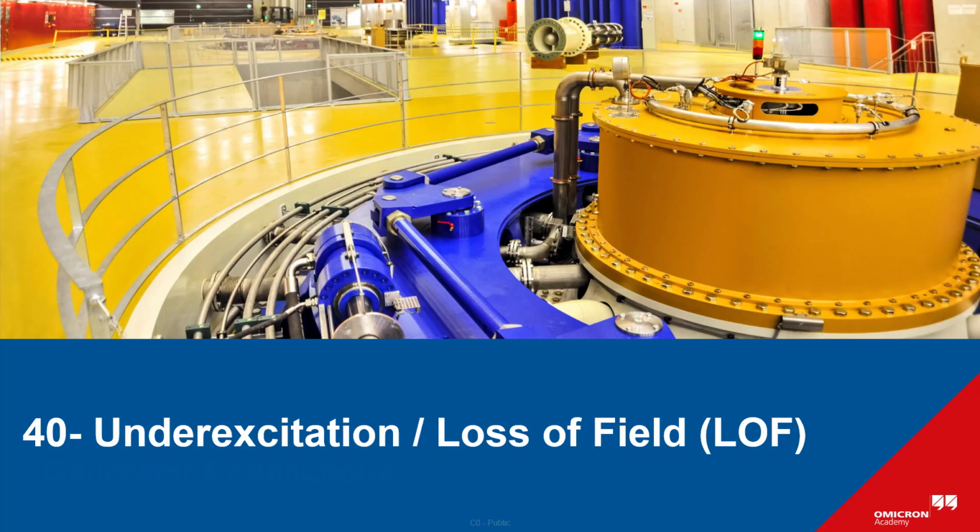In this video we will explore how loss of excitation affects generator stability and system voltage, and how protection can detect and isolate such conditions. We will also go through the practical testing steps, including how to configure the distance or admittance-based characteristic, import and organize the raw data, and perform trip time characteristic verification using the advanced distance module.